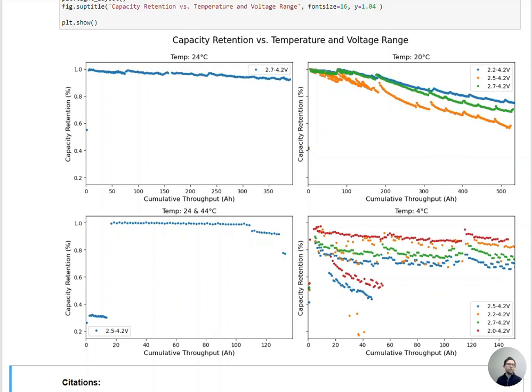So in this video, we've looked at the different battery cells in the NASA dataset, all 33 of them. We created a function to perform coulomb counting, and then we iterated through that function for all the batteries in the dataset and for each test condition. We identified and highlighted how it's important to always check to make sure that the headers are consistent when doing a large-scale data operation, such as reading 7,000 CSV files. And then we also highlighted how data cleaning is still required after you've read in those files, right? And that should be evident from these plots here.